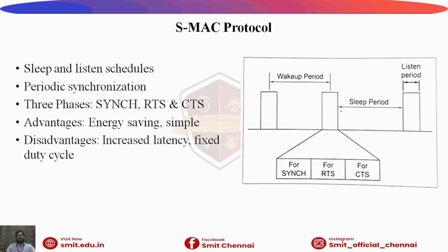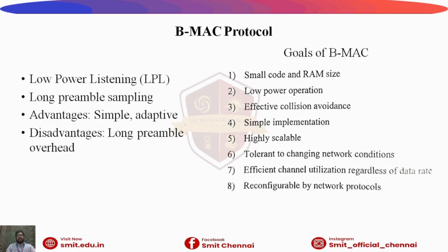RTS is the short form of request to send, and CTS is the short form of clear to send. It gives the advantage of significant energy savings, and it is very simple in design. The disadvantages of this protocol are increased latency due to sleep cycles, and a fixed duty cycle not adaptive to traffic changes.